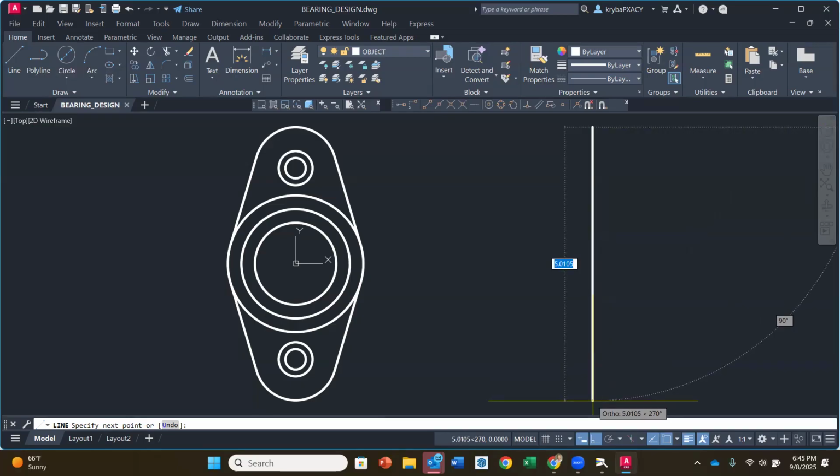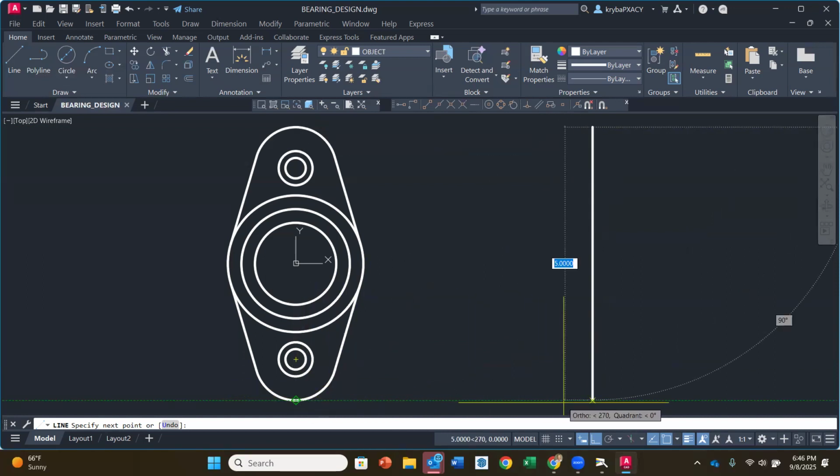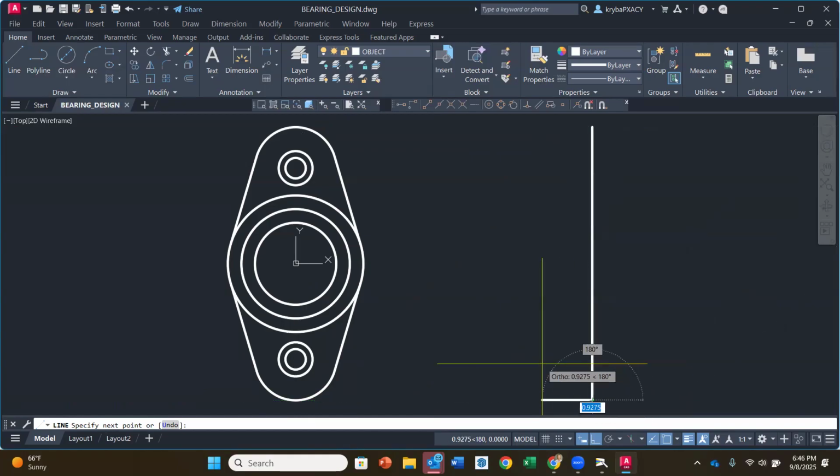Now, the next thing I want to do is I want to activate the bottom. Now, if you look at the part, you could add it together and say, oh, that's 5 inches. So you could push and enter 5 if you wanted to. Or we can activate the bottom here, kind of come back, and now you'll notice that we have that snapping reference line. So I'm going to just do that. Notice that it is 5, okay? Now I'm going to continue. I'm going to push to the left, okay?